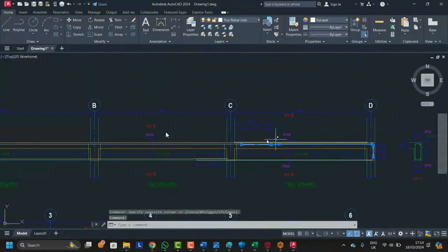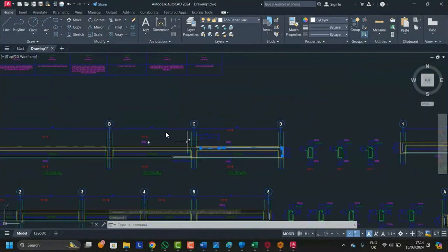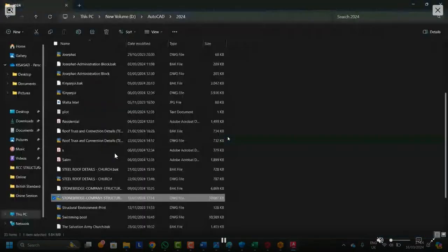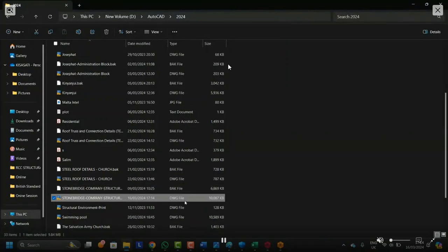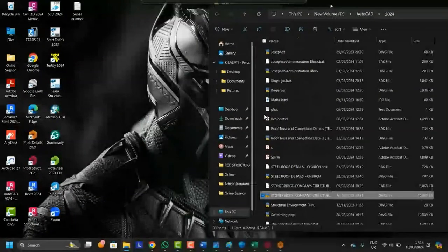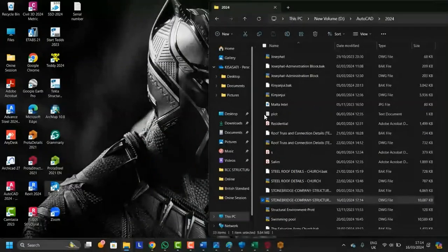You can unblock this beam, then curtail it well or lap it well at this point, but we will discuss that one later. So make sure you perform the precising, especially the columns, because if you don't do that, unnecessary moments will be created for the columns and the problem will now be for you, because you'll now have to figure out how to edit the columns which will have failed. It's actually tiresome, especially when using AutoCAD. ETABS, it's very easy.